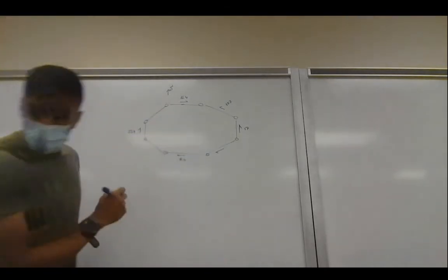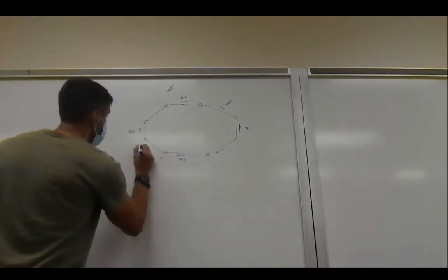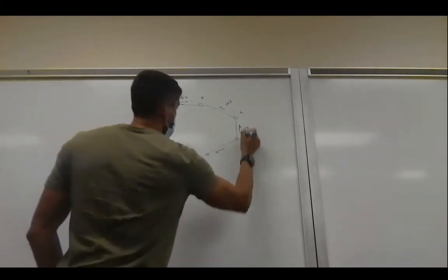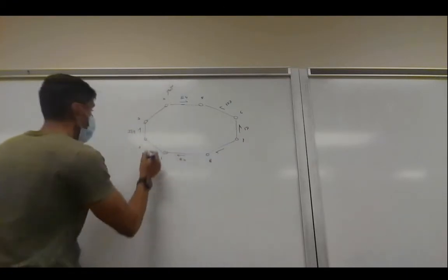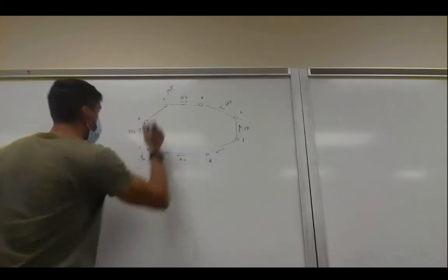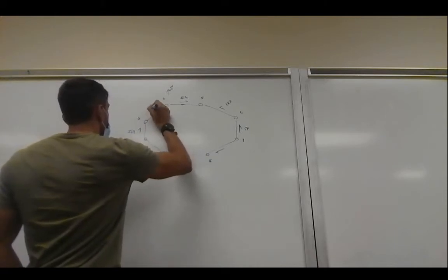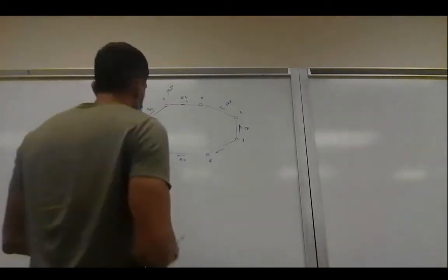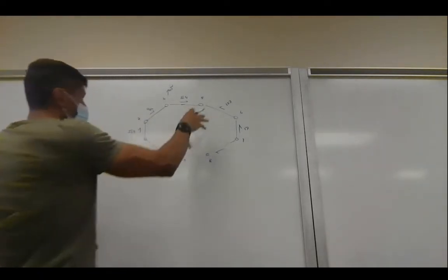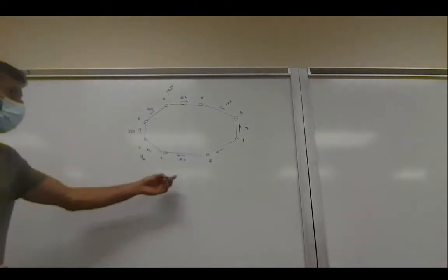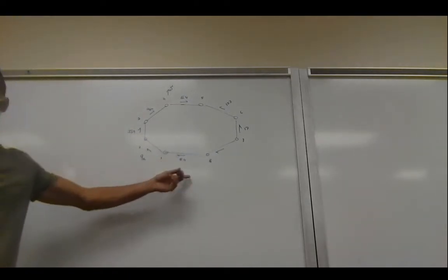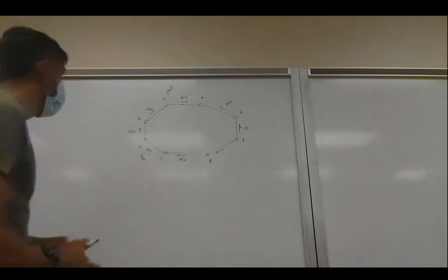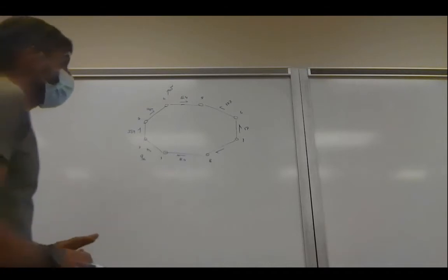And then we had Q1, Q2, Q3, Q4. So what most of you did, you said, well, okay, closed section, so they made a cut here, and they calculate the open shear flows. They find out, if you have made a cut in this 5.4, so this must be a correction shear flow, so you add it up and you got your Qs. Totally fine. But you can do it significantly easier.